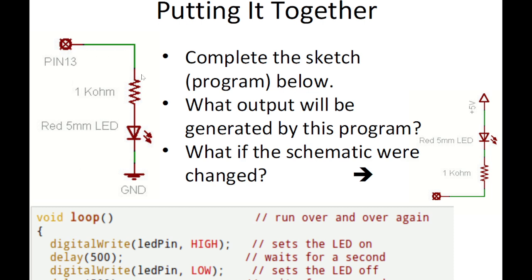And that's how you connect the example sketch we just did previously. At pin 13, you connect a resistor and then an LED to the ground in order to glow the LED safely. In this way, the resistor limits the amount of current drawn from the microcontroller pin. This example relates to simply blinking the onboard LED: making the LED pin high, then low, with a delay of 500 milliseconds.